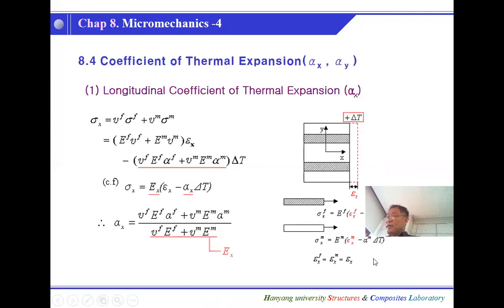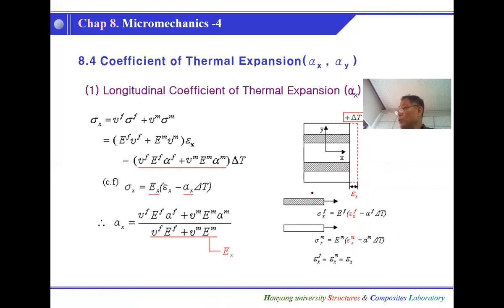And now CTE, just keep that in mind that we follow the constitutive relations of the fiber. This is the constitutive relation for the fiber, and this is the constitutive relation for the resin. Constitutive relation means the stress-strain-thermal terms for the fiber and the stress-strain-thermal terms for the resin. We just use these terms, and x-directional wise, we follow the rule of mixtures.